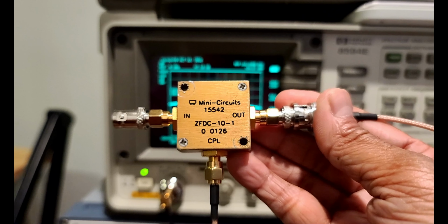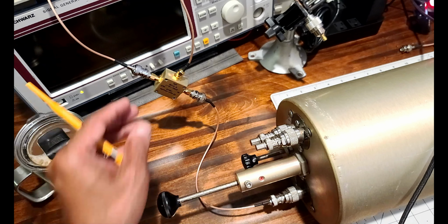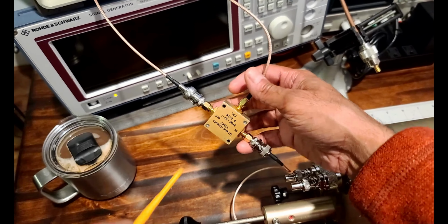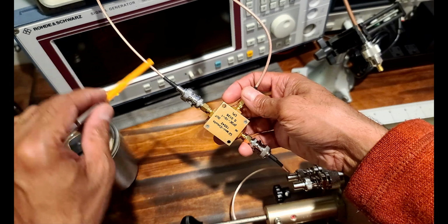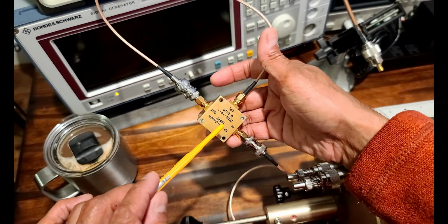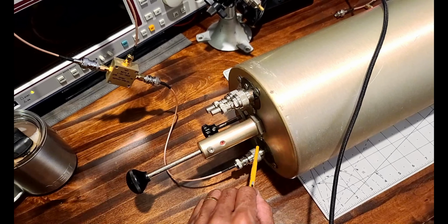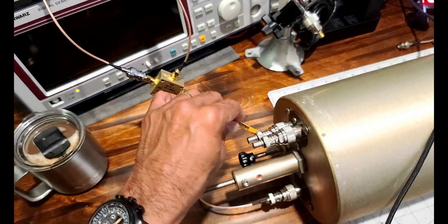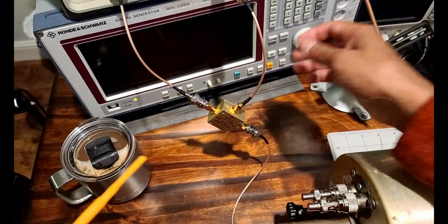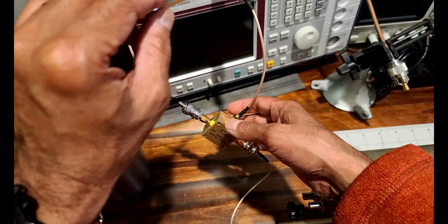So let me get this set up quick, and I'll be right back. Okay, so I wired up the equipment here. Let me quickly walk through what I've done. Right here we have the directional coupler. As mentioned earlier, the output from the tracking generator is fed into the coupler's output port, and the input port is hooked up to the cavity filter's input port. I've also terminated the cavity filter's output port with a 50 ohm dummy load. Last but not least, I've connected the coupled port to the RF input on the spectrum analyzer.